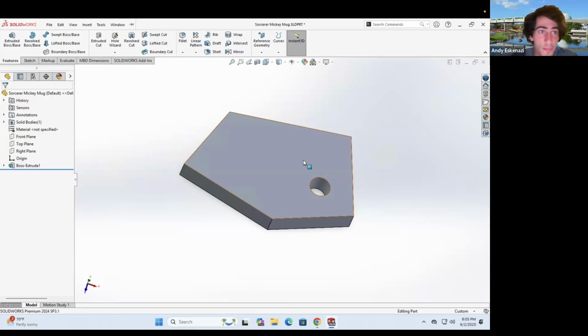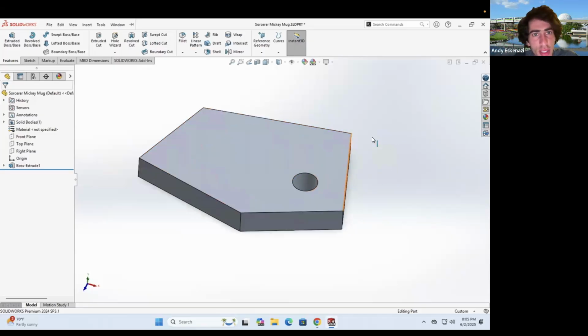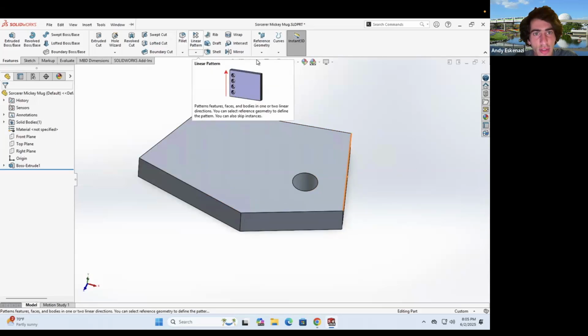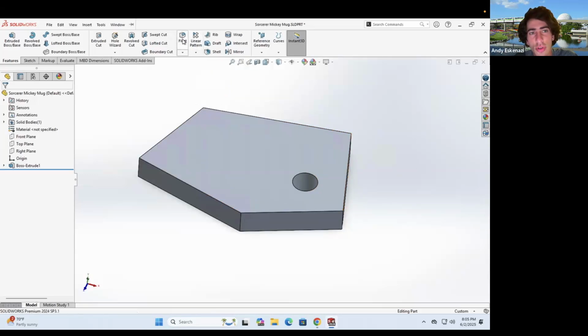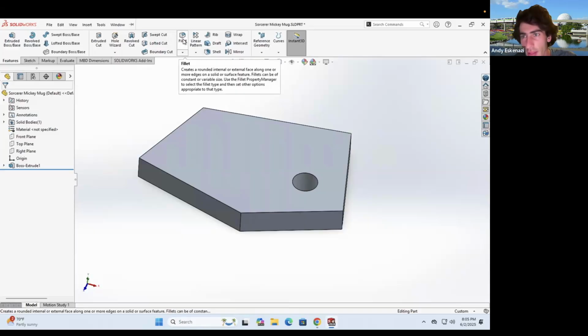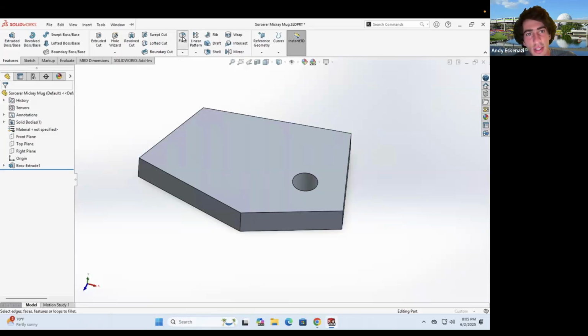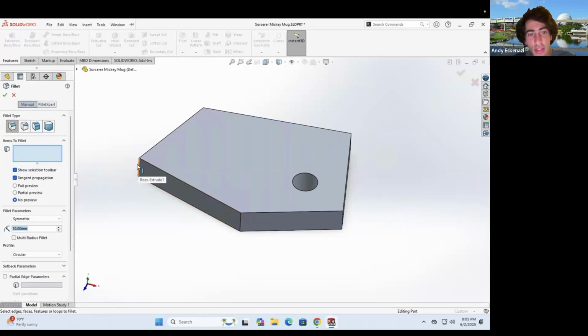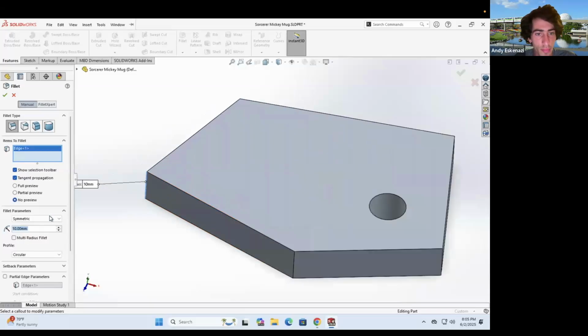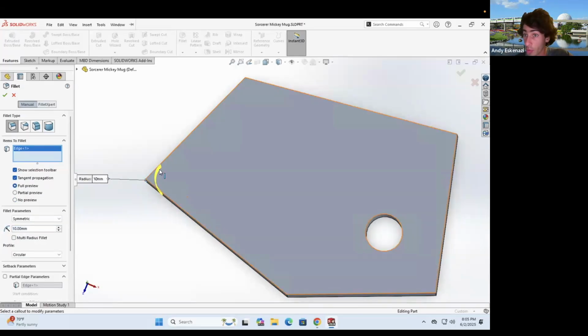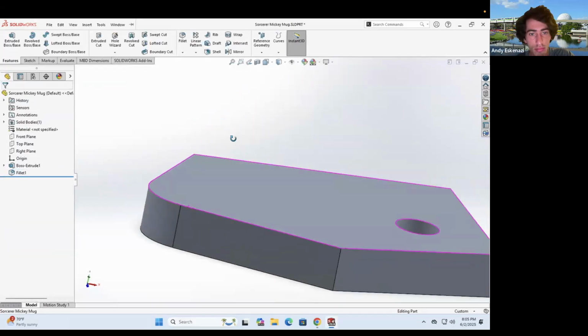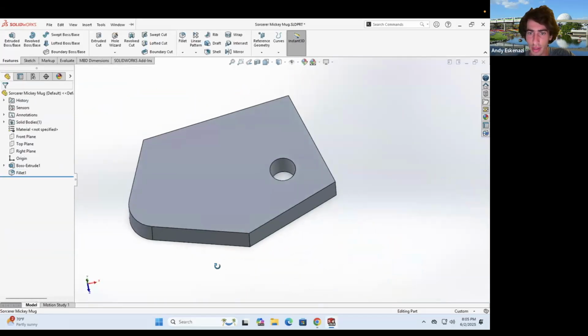this volume in 3D. Now, what you can do from here is go to special commands. One of the ones we're going to be focusing on particularly today is the fillet. What that does is that I can click in here and say, right, I want that, instead of being sharp, to be circular. So let's see whether it allows us to do that. I can go here to where it says full preview to see what that circular shape would look like. Maybe give it 20, and voila. That looks pretty round right there.